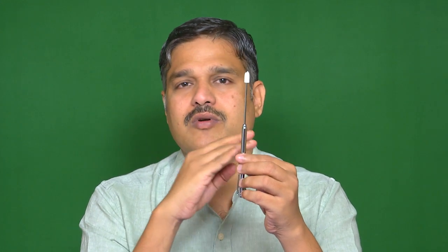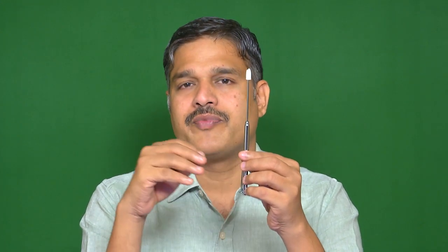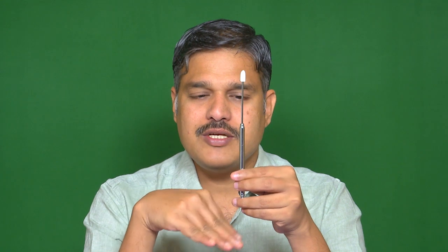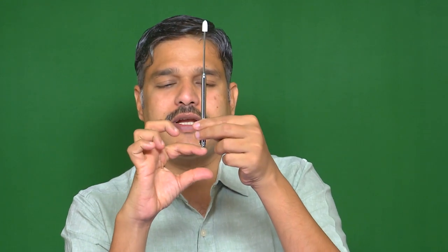So what we do is, say there are different techniques. One is called the active control method, another the passive control method. In the passive control method we have, say, a tuned mass damper, tuned liquid damper. There are other techniques, but there is a very popular technique called the base isolation technique. This technique will not allow the vibration energy to enter inside the building. So that means we are isolating the building.